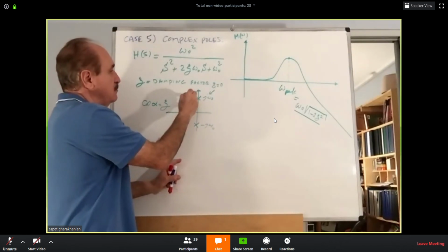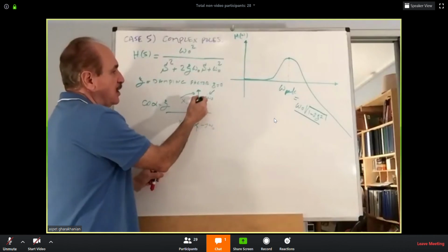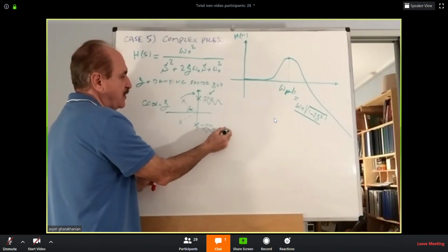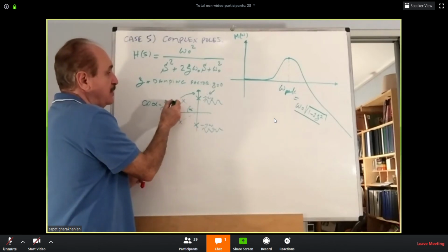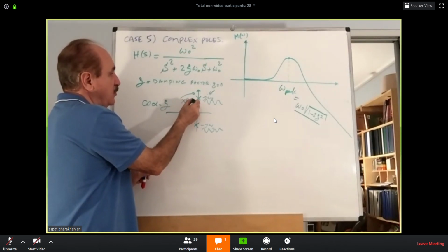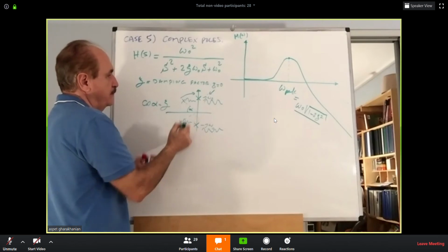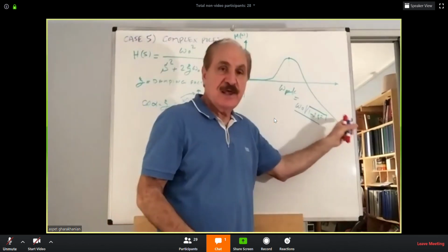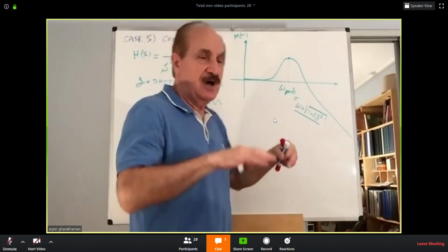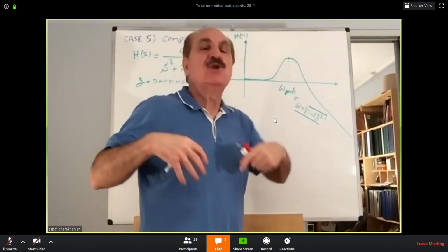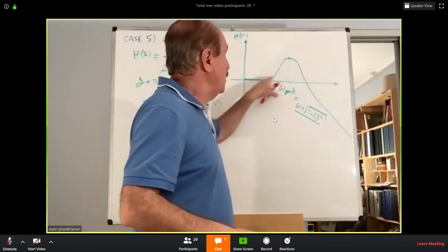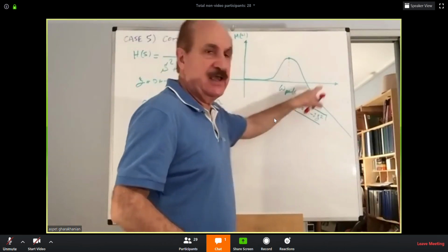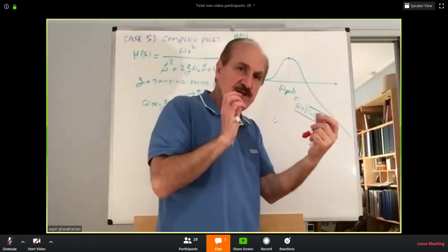The poles in here will oscillate forever. The impulse response will be oscillatory, but the impulse response here will decay, will die down. So it is related. If a system is underdamped, it will show in the frequency response domain. You will see a peaking when you're applying a sinusoidal test input.